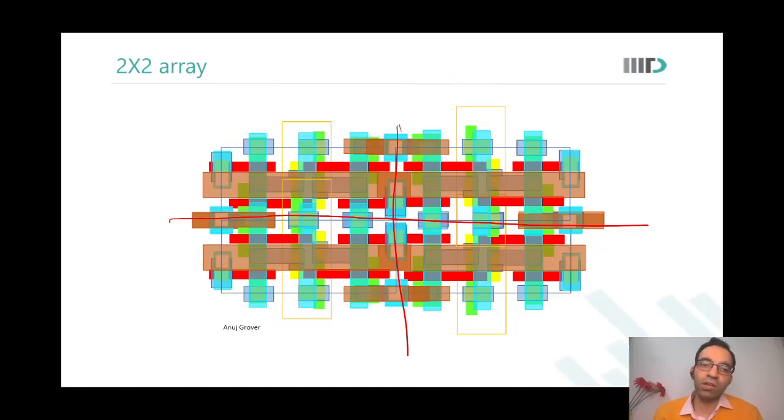If I would not mirror along this axis, there will be a disconnect. I wanted to connect a bit line on the pass gate, and I need the bit line on this side. If I just translate it up there, there would be ground from this side and bit line from this side. I cannot merge them. Therefore, mirroring on this side is also required.